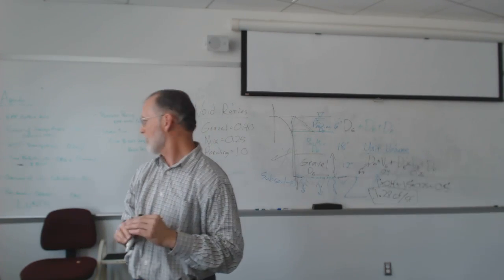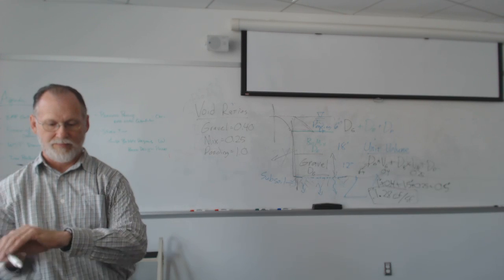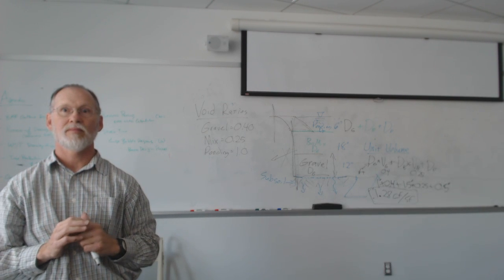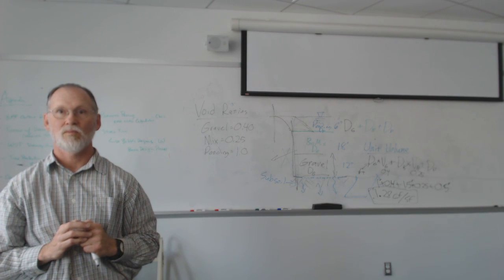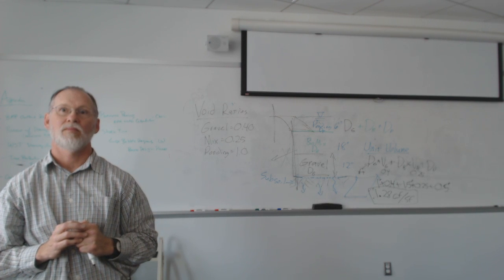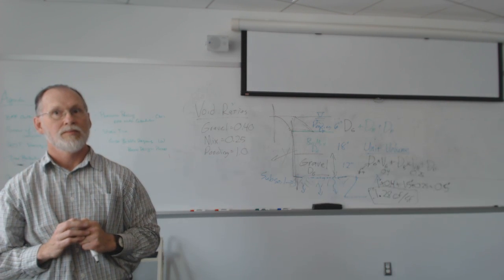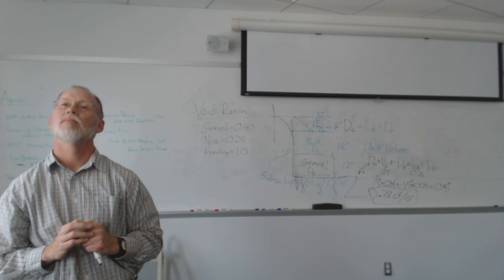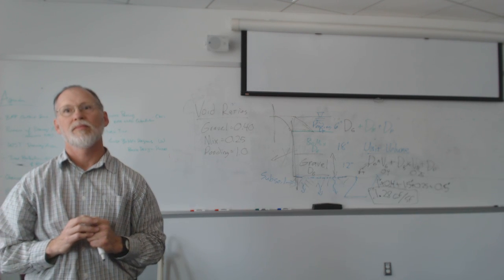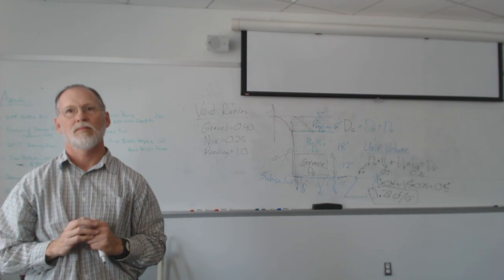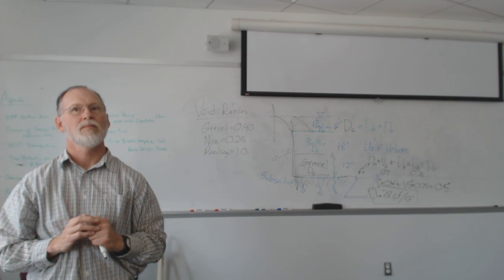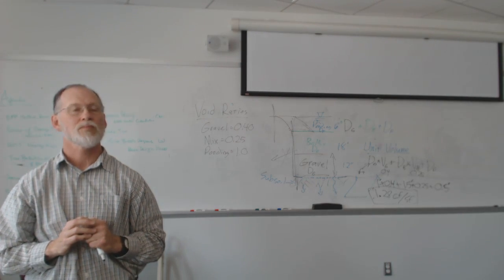Imagine you adjust based on the surface area you have available and how much water you want to absorb. You used a ratio of about 1:3:2 for ponding, biomix, and gravel. Is there anything magical about that ratio?